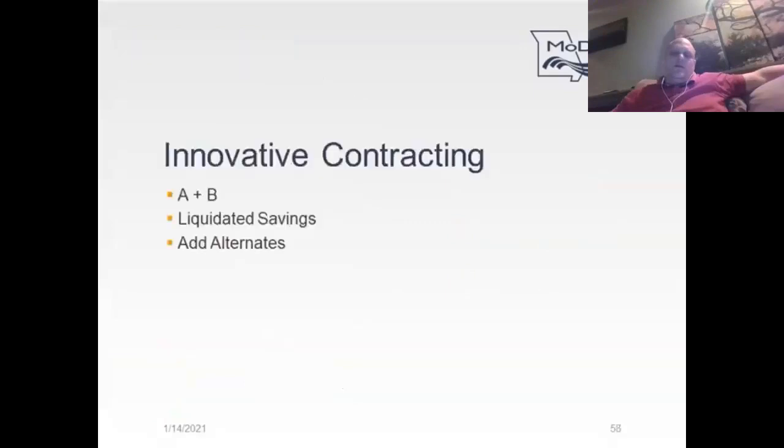Innovative contracting: there are a few innovative contracting methods that can help you hit your program amount when you're setting it. You may choose to include any of these incentives for your project. For projects that have necessary milestones, it can be beneficial to provide an incentive for achieving those milestones. EPG Section 237.8, contract time, gives more detail on the different incentives and disincentives that may be used. For positive reinforcement, there are two incentive methods that will impact your program if used.